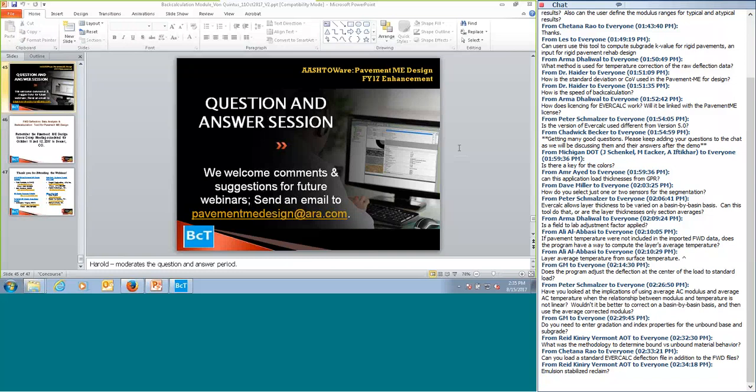What I typically use in terms of establishing whether that's a bound or an unbound material is if I see the back calculated values like the test section, LTPP test section in Arizona, which used a base material from the Salt River aggregate source. It has fines in it, and if those fines become very dry, they act like a cementitious type of material.